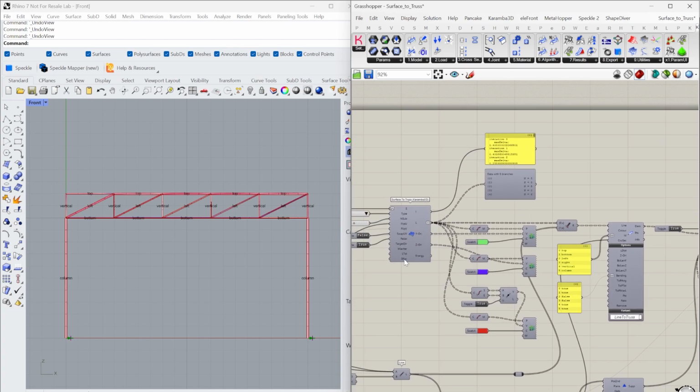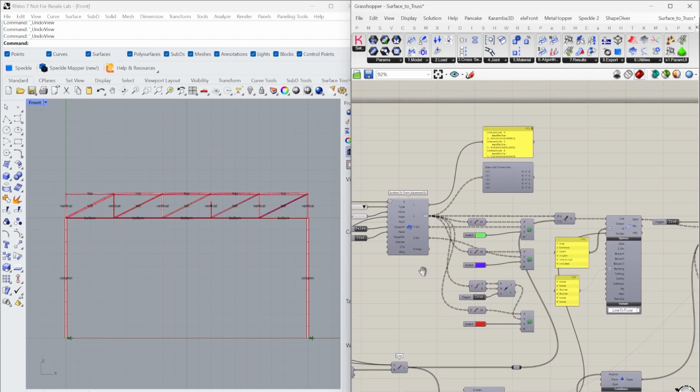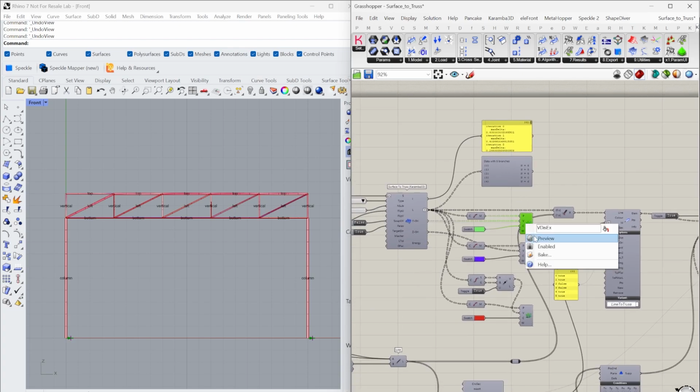Additionally, the orientation of each element along the Y and Z axis is also made available. This offers more clarity for structural interpretation and modeling, and these directions can be used to orientate the beam local directions and thus cross-sections, local loading directions, or hinges.